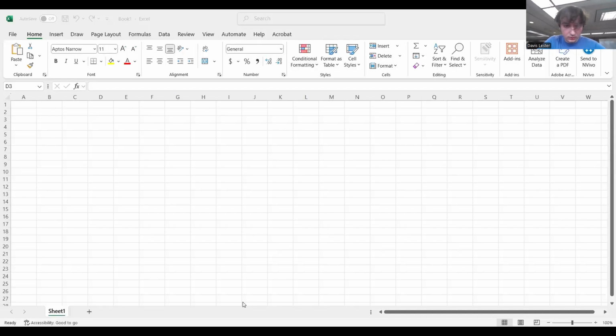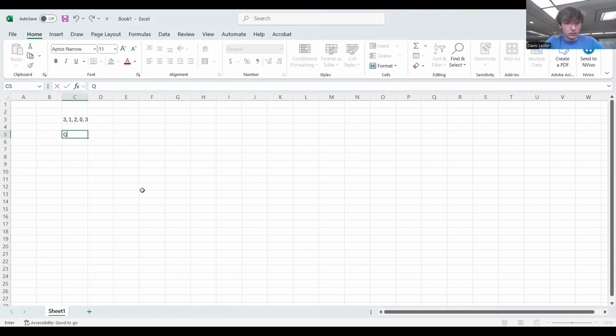Okay, so the count was, if I check in PowerPoint real quick, the count is 31203. Okay, so let me just write that down. 31203. Okay, so now the biggest count is going to be 3. So that means we're going to need 2 bits to represent it. So we can have Q1, and then Q0, and then Q1 plus, and Q0 plus. So this represents our next states.